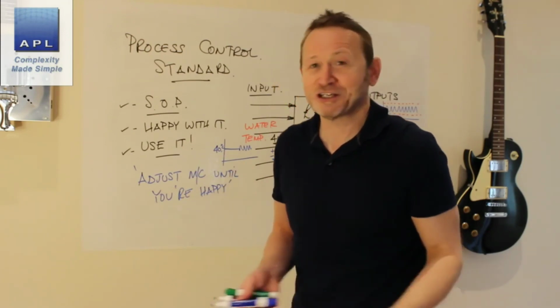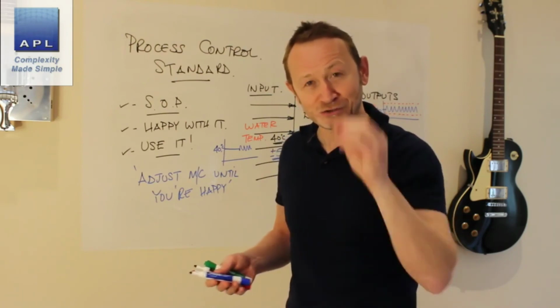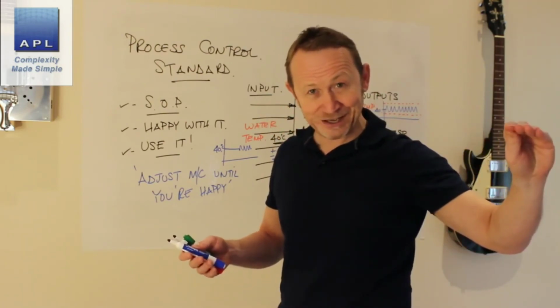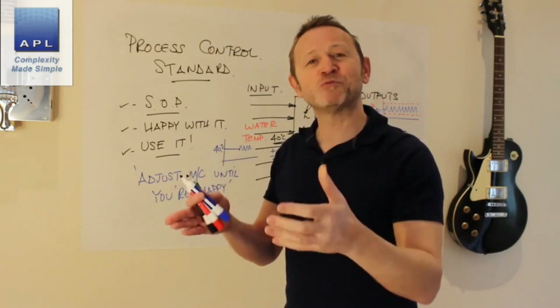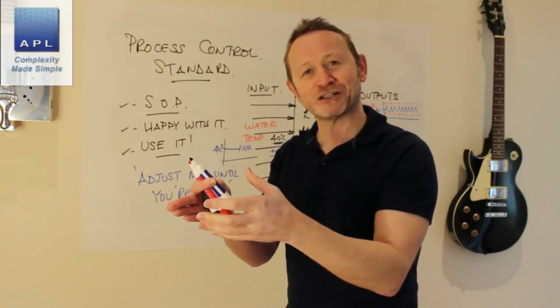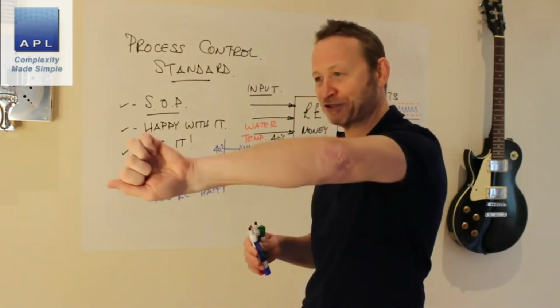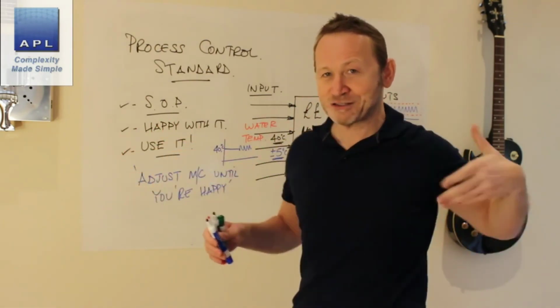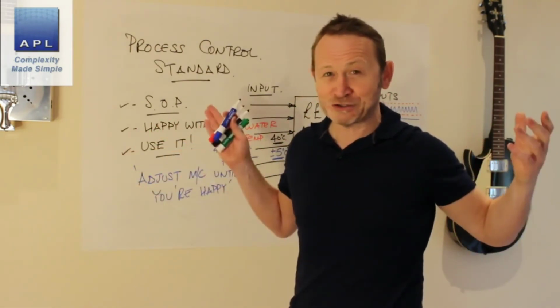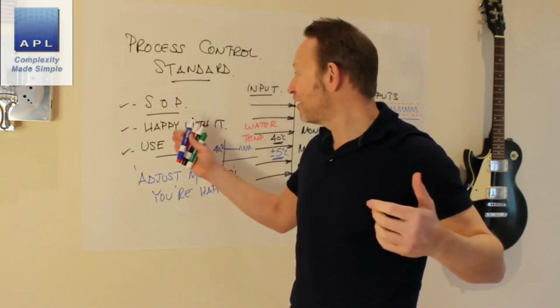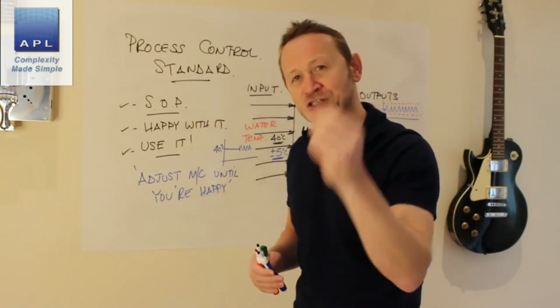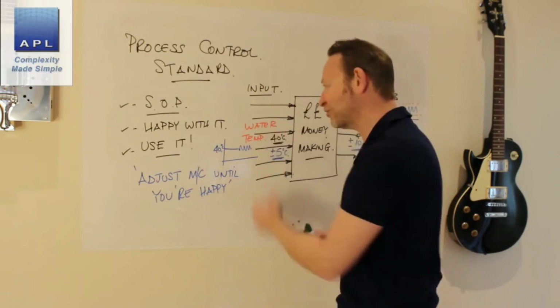Now in that case, you can't hold that tolerance. You can't hold it. It's exactly a particular flow, it would be wrong to try and specify it like that. But in this case, if I dial the thing to 40 degrees, take my hand off the dial just stays at 40 degrees. I don't need a tolerance. Don't give them when they're not necessary.